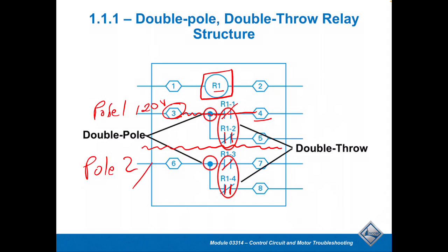And if I also have 120 volts here, I would expect this to go from 6 all the way through to terminal 7. And then there would not be any power, or I hate to use the word dead terminals, but they're terminals that are not going to carry any current flow, which is going to be terminal 8 and terminal, not 4, but terminal 5.